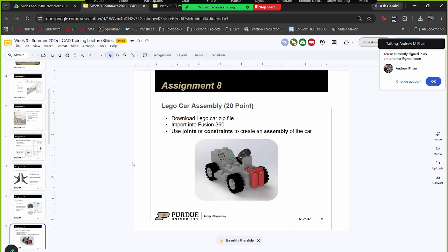And the reason I recommend that is because the first part you add into an assembly is grounded by default. So if you remember the fix/unfix constraint, grounded is the assembly equivalent to that.